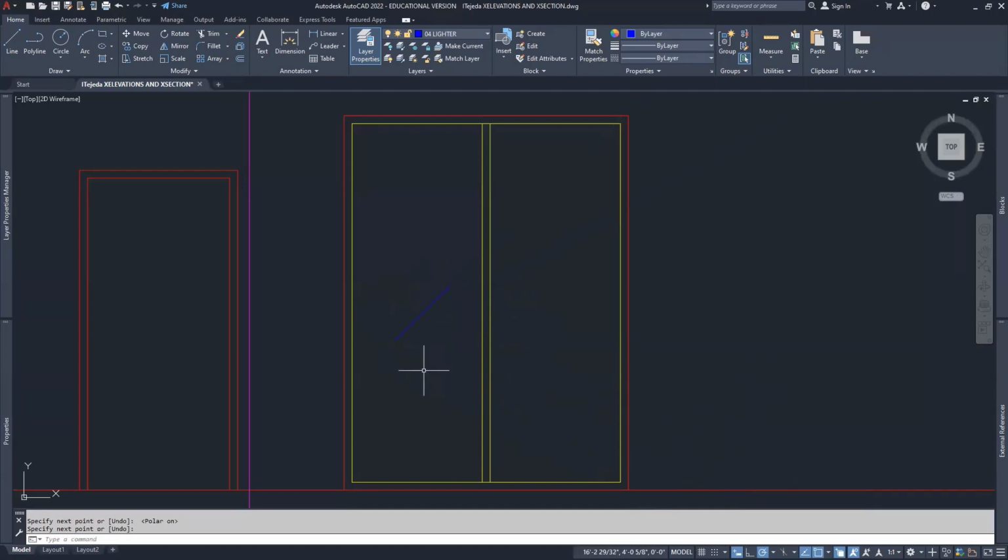And then I'll draw another line. Or actually, no, I'm going to copy that one. So I'm going to type in CO, enter, take that line, enter. And I'm just going to move out here. Click right there, turn my polar tracking off. I'd like to make a copy here and another copy right there. There's no exact science here to it.